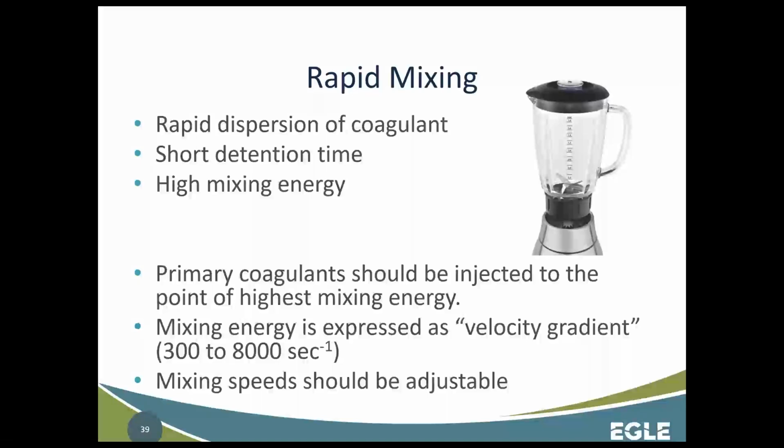They look at mixing energy as a velocity gradient. Units can be weird sometimes. So the velocity gradient is expressed as inverse seconds. The mixing speed should be adjustable on whatever device you're using.